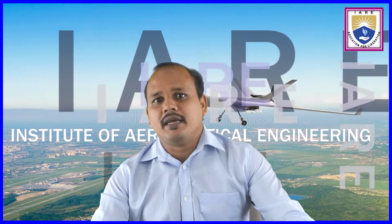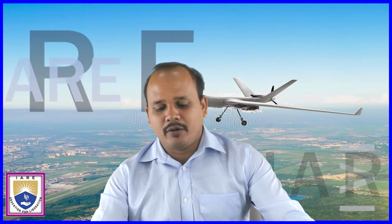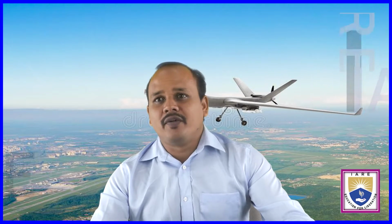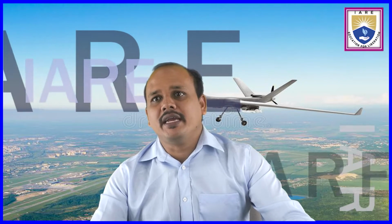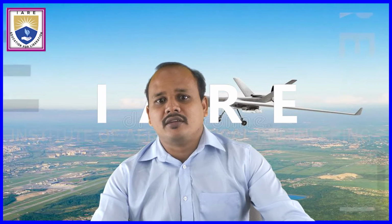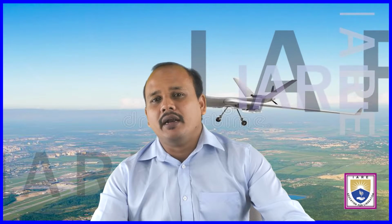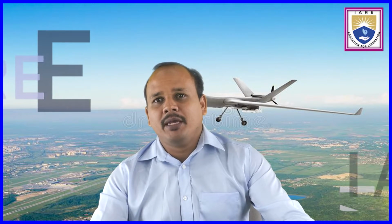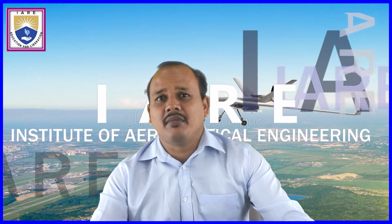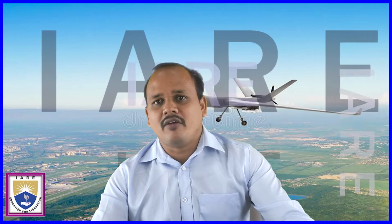In the Pitot type intake, we have seen the three types of intake and where exactly we use a particular type. And later on, we discussed the different operation modes of a subsonic intake. That is, during ground, static flight operation, how does the Pitot intake perform, and when we start climbing, how does the intake perform, and when you fly at the cruise speed or design Mach number, how do they behave, and then when you overspeed your aircraft, how do they behave.